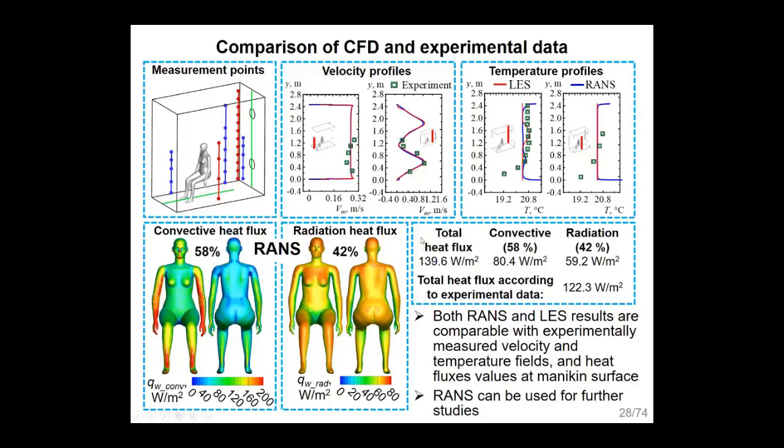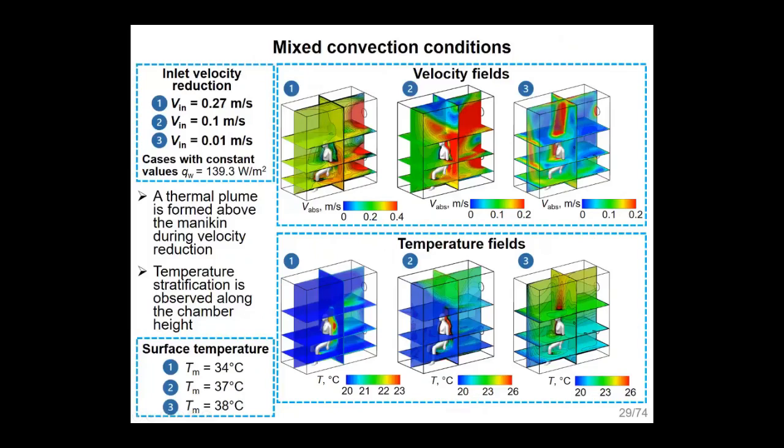Then we performed quite a large number of computational runs to study the effect of the thermal boundary condition at the surface of the mannequin, and to study the effect of radiation, which is very important for this particular problem. Up to 50% of the total heat flux is due to radiation here.